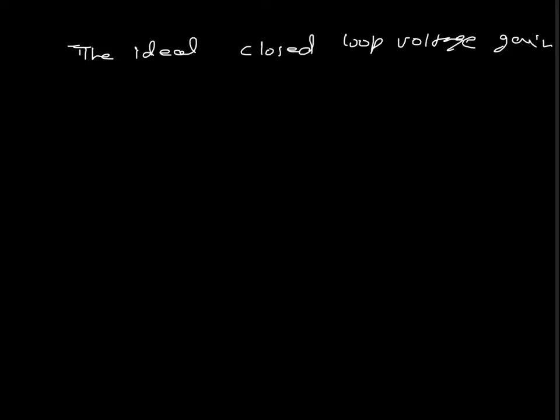So the expression is IC equals IE, which is VE by RE. VE means VBB minus VBE. This VBE is ideally 0.7 volt for silicon, and this VBB we can find by using this formula. It means the value of IC can be found by using this approximate analysis. So this is the first expression. Now second, as per the question, we need to find VCE.